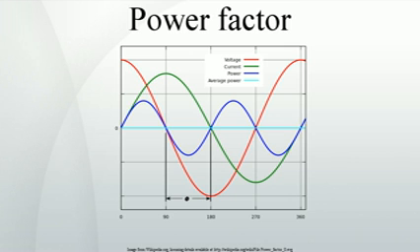The presence of current harmonics in a transformer also results in larger eddy currents in the magnetic core of the transformer. Eddy current losses generally increase as the square of the frequency, lowering the transformer's efficiency, dissipating additional heat, and reducing its service life. Negative sequence harmonics, 5th, 11th, 17th, etc. combine 120 degrees out of phase, similarly to the fundamental harmonic but in a reversed sequence. In generators and motors, these currents produce magnetic fields which oppose the rotation of the shaft and sometimes result in damaging mechanical vibrations.